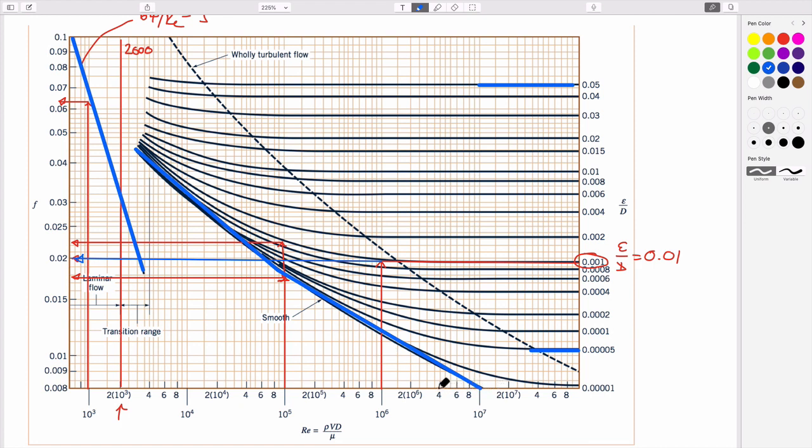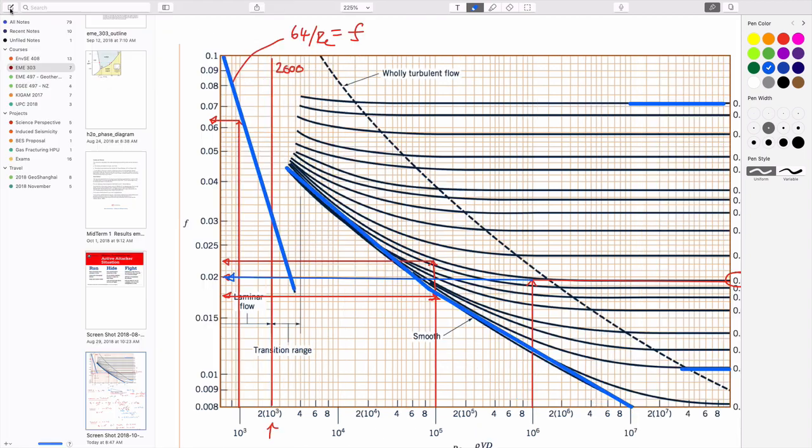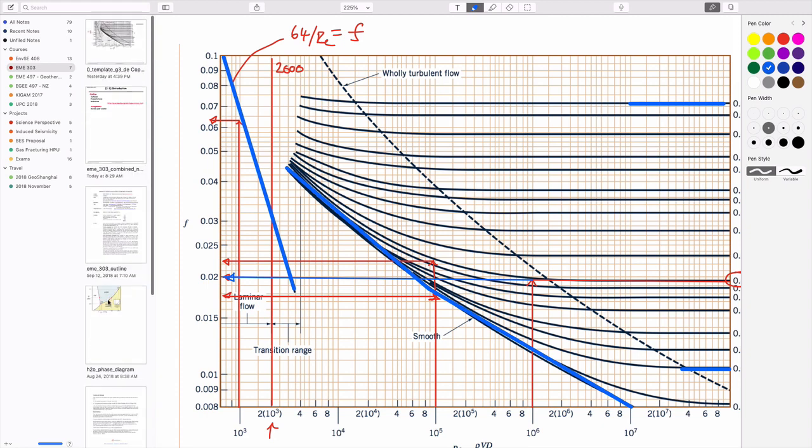And so that's kind of a bit partway in between the turbulent regime and the laminar regime, in that there's never really a single magnitude of friction factor for a smooth pipe because it varies throughout the range. So it's a bit like a laminar pipe, but we don't have a neat closed form solution to say it's 64 over Reynolds number. It's some different number, and you have to take it off the graph. And so merely making the point that when you go through this, sometimes you have to iterate to get a solution if you're in this regime where we're in these so-called type 2 solutions that we've identified.